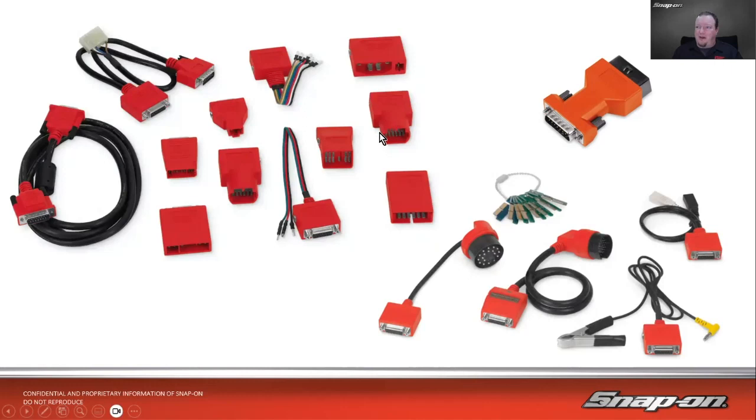Bunch of other manufacturers. Jeep had a different one. This one's kind of a universal one where you put the pins in different places. Of course, you need an adapter to adapt it to the scan tool. In some cases, it was a cable on the older ones. On the newer ones, it is just a 16 pin OBD2 adapter to the 15 pin on the other side. And then you're able to communicate with the vehicle that way. So there's a lot of different manufacturer differences, and that's what OBD2 helped us with.